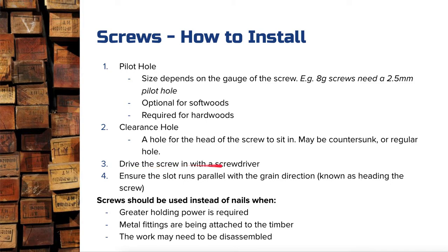You can drive the screw in with a screwdriver. The idea here, I know everyone is used to getting the impact drivers and just driving those screws in because it's easier and it's faster, and that's totally fine. But if you can't put the screw in by hand with a screwdriver, then you have not done your pilot hole correctly, or you have not done your clearance hole correctly, or you have not done your countersink hole. Okay? Wrong sizes, wrong length, something going wrong there. The screwdriver should be enough. It shouldn't be hard to put a screw in, but at the same time, it should bite into the timber to give you that pulling strength.